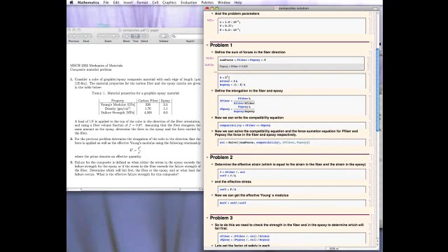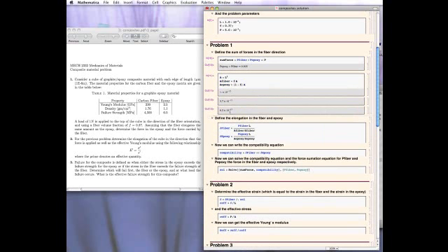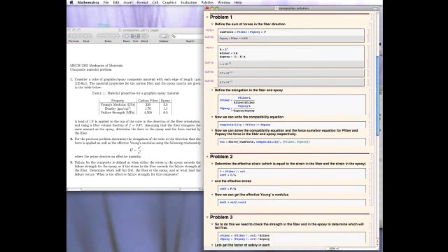Now let's get the cross-sectional area. That's the length squared. The area of the fiber is just the volume fraction times that area, and the area of the epoxy is 1 minus the volume fraction times that area. Shift Enter. These are the actual values. They sum to the total area. So here's the total cross-sectional area, here's the cross-sectional area that's fiber, and here's the cross-sectional area that's epoxy. All right.